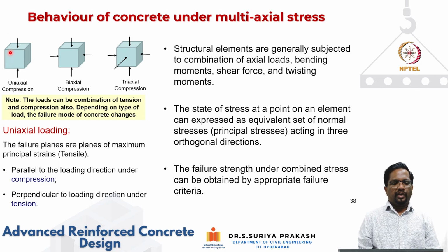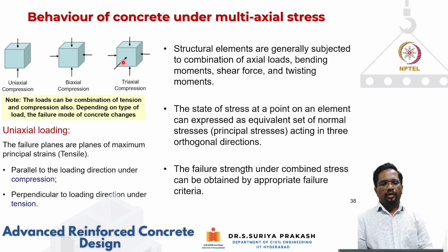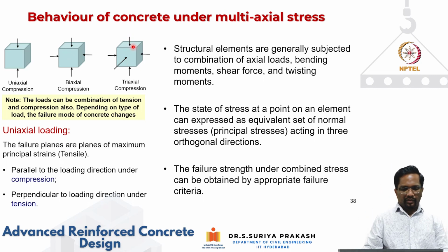But you can also have biaxial compression that is shown here, or sometimes a system can also be subjected to triaxial compression. So if you have equal compression on all sides, we call that hydrostatic stress. Okay.